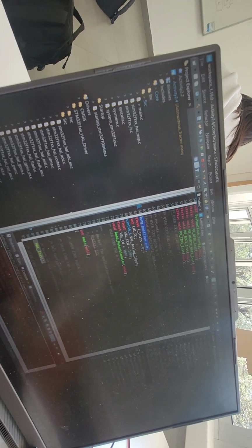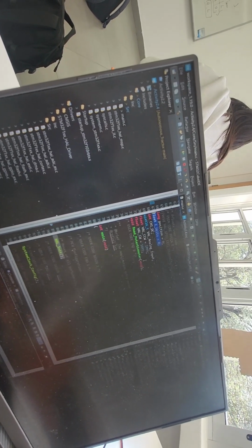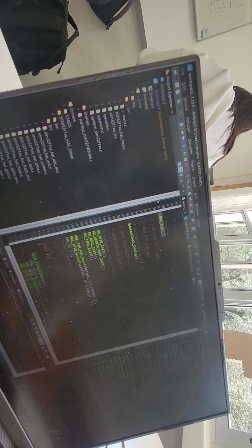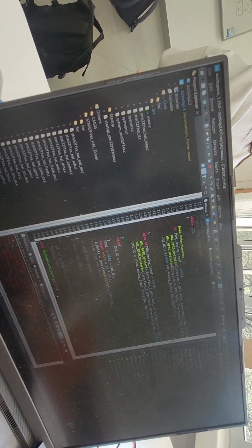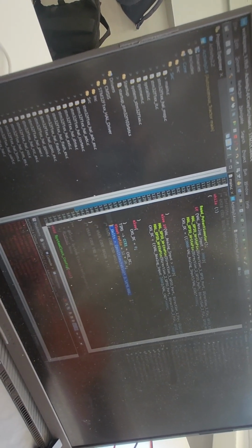Then we declare another variable, the meter unit, and that value we are then translating into units of measurement, which is in meters. The ratio of our encoder is 12 ticks per revolution, and we have a 20.4 reduction gear.